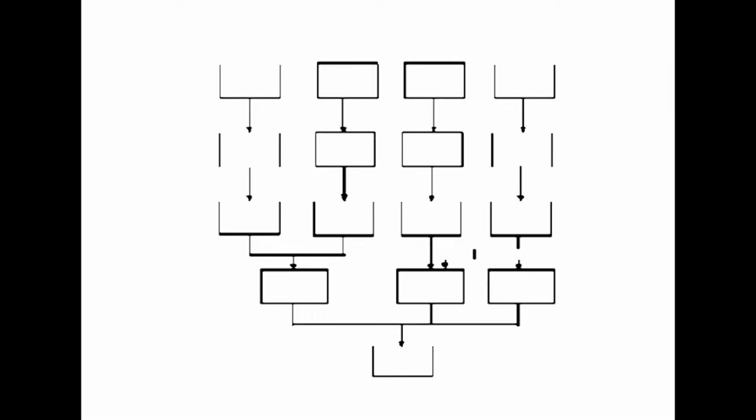Control charts for variable data are used in pairs. The top chart monitors the average, or the centering of the distribution of data from the process. The bottom chart monitors the range, or the width of the distribution. If your data were shots in target practice, average is where the shots are clustering and the range is how tightly they are clustered. Control charts for attribute data are used singly.